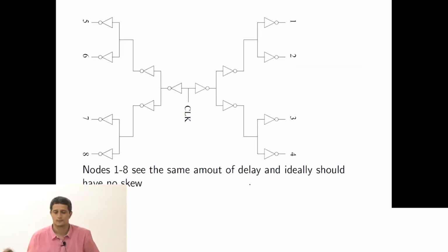What you do is, the clock generation happens at a central point in the chip, because the clock has to be insensitive to temperature, voltage changes and all that. So you make a PLL based clock or something like that, which is very stable and has no jitter. What is jitter? Basically the clock edge just moves around a little bit randomly. With time, one edge can go this way or that way. So you want to design something with lower jitter, and then you distribute this clock through the entire chip in a tree-like fashion here.